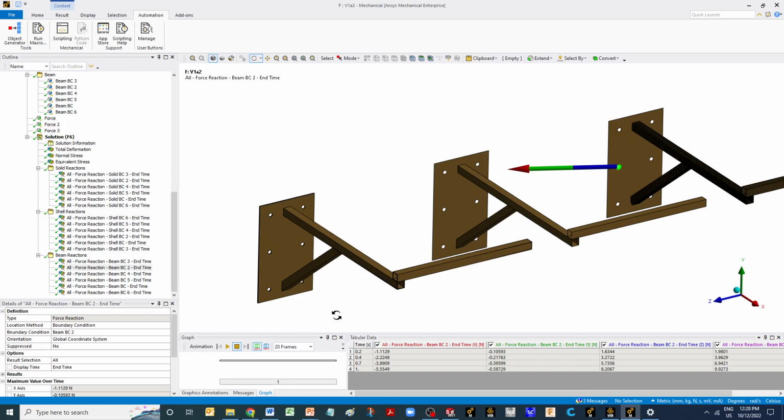So when the failure happens, these are one of the most critical areas: the bolted connections, the bonded or welded connections. Typically, it's very easy to design a structure to sustain the loads based on simple flexure formulas. The beam formula, the torsion formula, and the simple column formula. We can also design a structure for buckling resistance.